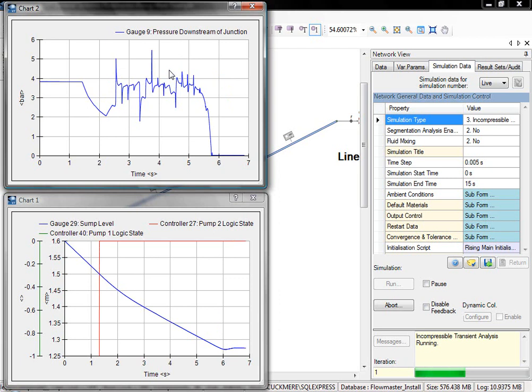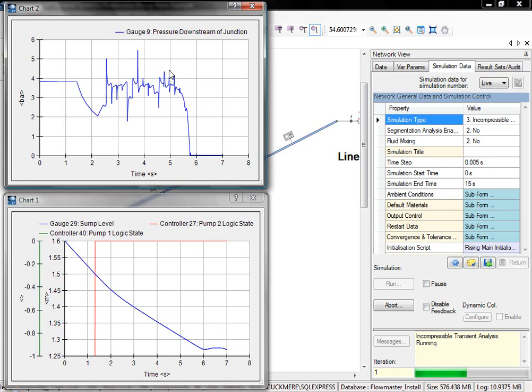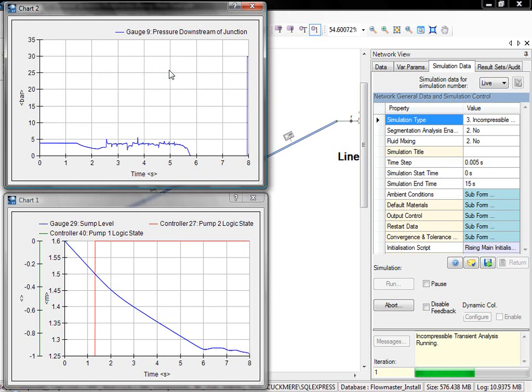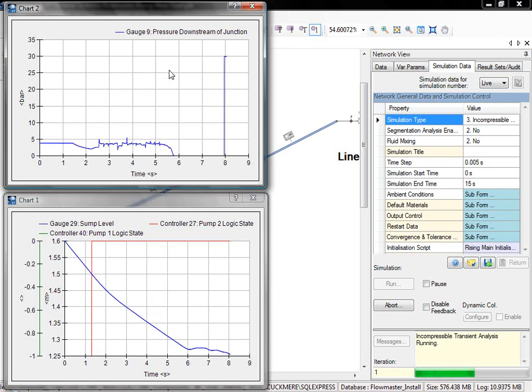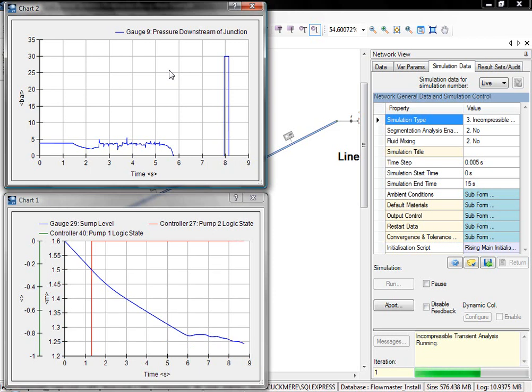as the fluid changes velocity. So here you can see the pressure peak caused by the cavity collapsing. Then, as the fluid returns, again we get a further vapour cavity. The analysis will now be run to the finish, and we'll look at the results within Flowmaster.